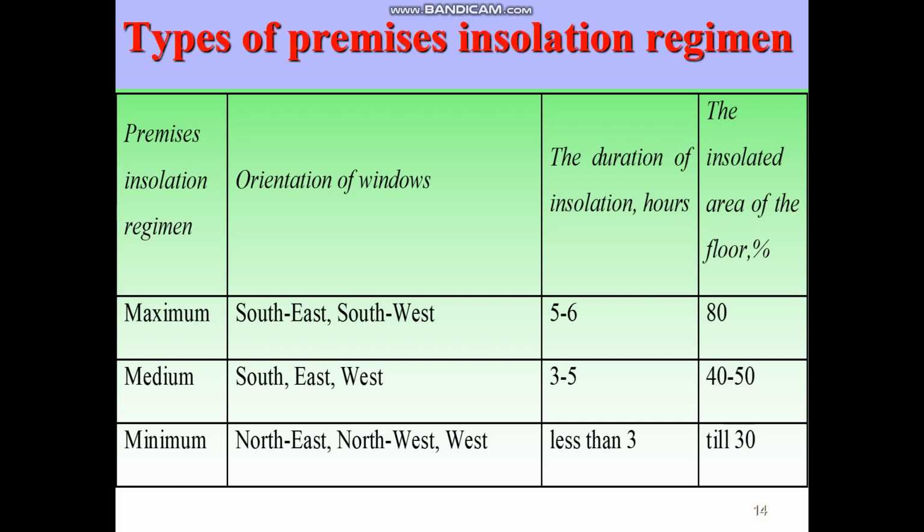Light energy acts on many physiological processes of the organism. In all premises assigned for long stay of people, the lighting by direct and diffuse solar beams is necessary. Lighting should be intensive enough, uniform, matte, but not forming hard shadows. For estimation of lighting conditions, the International System of lighting values and units is accepted.